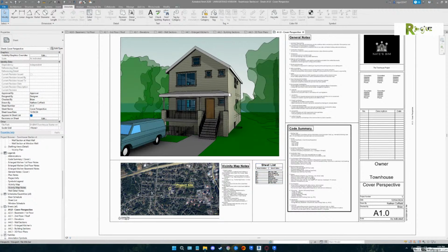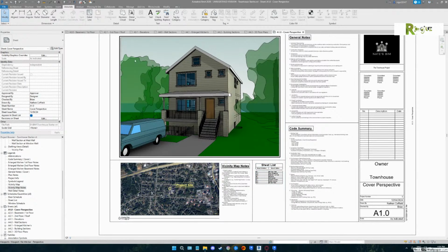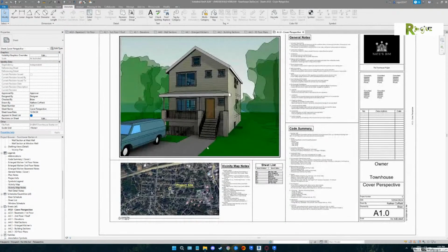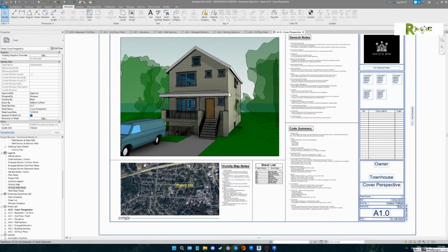So all these notes that are only going to appear one time are better off as drafting views, because then you can copy them from house 1 into house 2. You only want to use legends if it's going to be on multiple sheets. Okay, I see. And not the end of the world. I do not recommend going and fixing it. Just trying to let you know. But that's a good question. You went overboard on the legends. Most of those I would want as drafting notes.